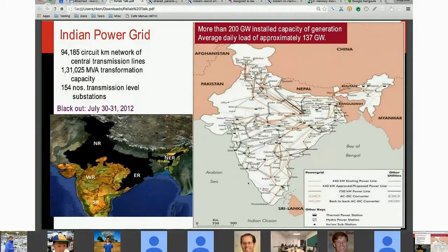That gets them worried because they now try to figure out what is happening, right? This is a very difficult problem because if you know what your fault is, you can simulate the fault and find out the effect of that fault on the patterns of the disturbances that you will see on the PMUs. But if you see the patterns of disturbances, the reverse map is not so easy to do, right? And that involves a way of formally trying to establish which is causing what.